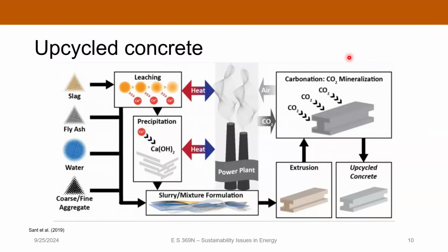But what upcycled concrete refers to in this context is actually adding CO2 to the concrete. And this has a lot of advantages. What they do is add the CO2 in an extra mineralization step after the concrete is made. And the CO2 gets in there, and it actually enhances the strength, and I think offers some corrosion resistance also to the concrete. So it can potentially be a good thing.